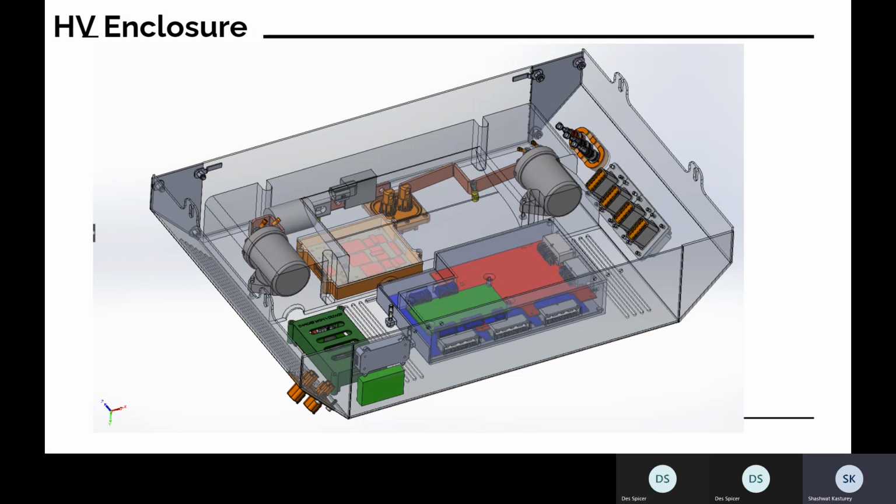If you power the 2 relay close pins, the battery pack will flow energy through those bus bars out of the HVD, the high voltage disconnect. That's that big orange thing I'm pointing to. These relays just manage the on and off switching of the battery pack.